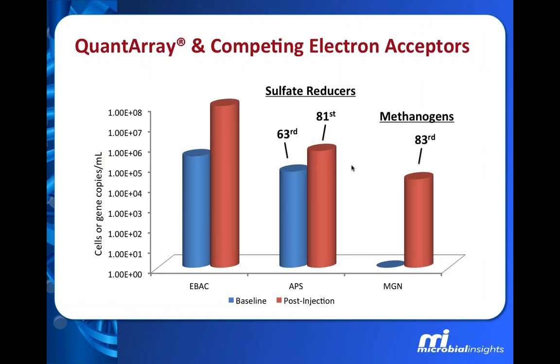Since this site is impacted by chlorinated ethenes, and we also have some chlorinated ethanes, with the dichloroelimination of 1,1,2-TCA we're going to get more vinyl chloride. Dehalococcoides is definitely going to be needed for complete reductive dechlorination of those chlorinated parent and daughter products. But if this were my site, these results would help alleviate my concerns that DHC wasn't quite to that 10 to the 4 threshold and that there were low vinyl chloride reductase genes.